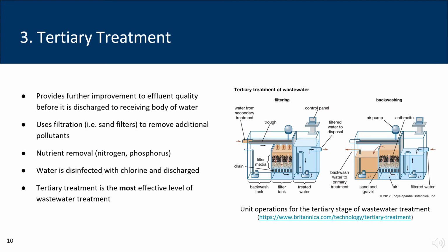Finally, tertiary treatment is the polish phase to water treatment. Primary and secondary get water only clean enough to discharge into the environment. However, tertiary works to clean water for intensive processes or even drinking water. Tertiary treatment is also beneficial when facilities must discharge water into sensitive aquatic ecosystems such as estuaries, sluggish rivers, or waters close to coral reefs.